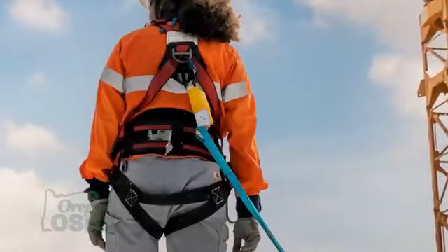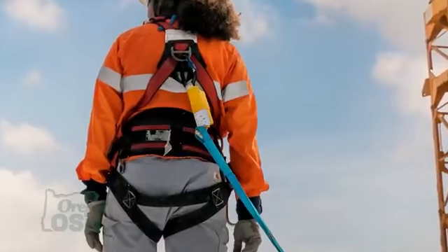When we're working with a fall arrest lanyard, that means making sure that the shock pack, the shock absorbing device on that lanyard, is always attached to the worker's back D-ring. The reason for that is when we fall over a leading edge, we create a point of friction. We've got that pinch point that's there.